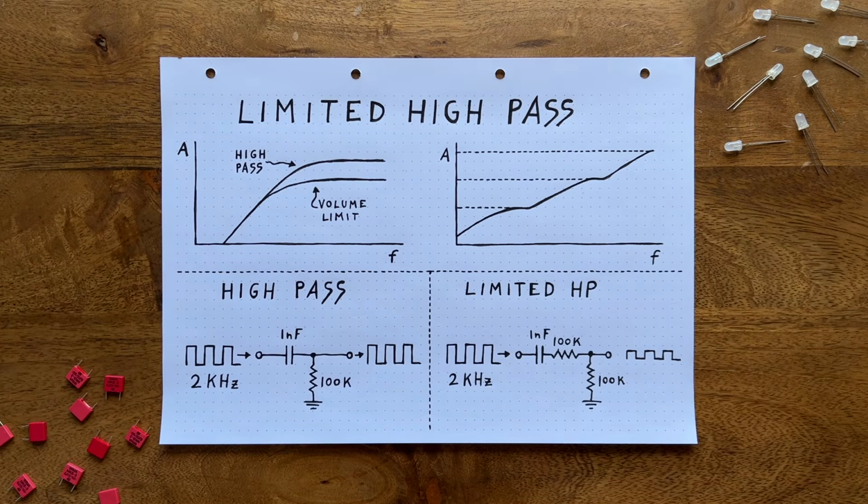Let's imagine that we apply a 2 kHz square wave here. Then the amount of current flowing through the capacitor in the wave's high and low phases is so small that it never builds up a significant amount of charge, which is why its resistance stays very close to 0 the entire time. And in a voltage divider, if the input resistance is very weak in relation to the resistor going to ground, the output voltage will be almost identical to the input voltage.